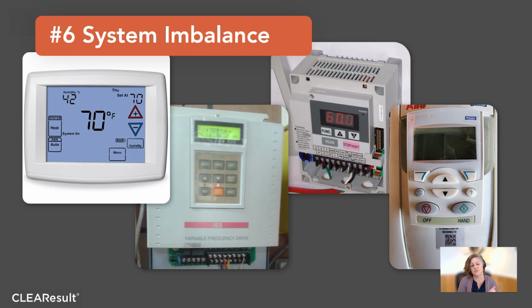So not only is the VFD not turning down and you're not getting the energy savings from operating at a lower speed, you're also wasting energy by running the VFD. So if you walk through and you take an inventory of every VFD, see what speed it's at. If you see one that's either on manual at 100% or at 60 hertz, either turn it down, figure out how it can be turned down, or rip that VFD right out because it's actually penalizing you.